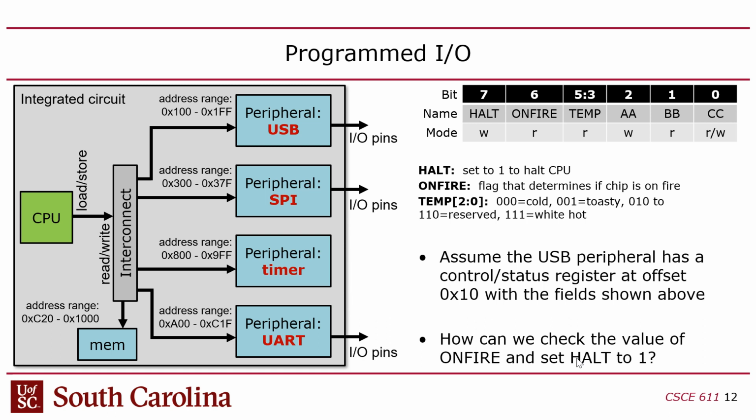You read it, and then you AND the most significant bits. Yeah. Well, that'll isolate those bits. You can bit mask and isolate, but then they're going to be in the middle. You don't necessarily want them to be in the middle. You want to use them, yeah.